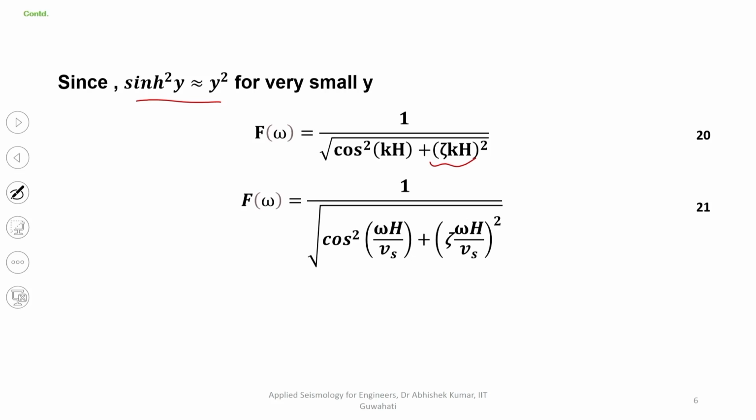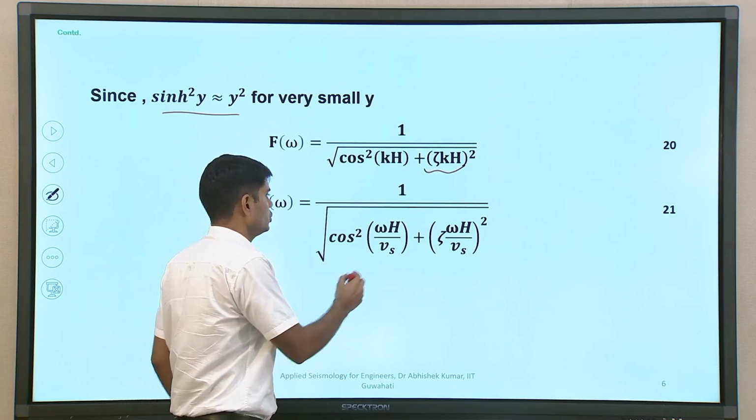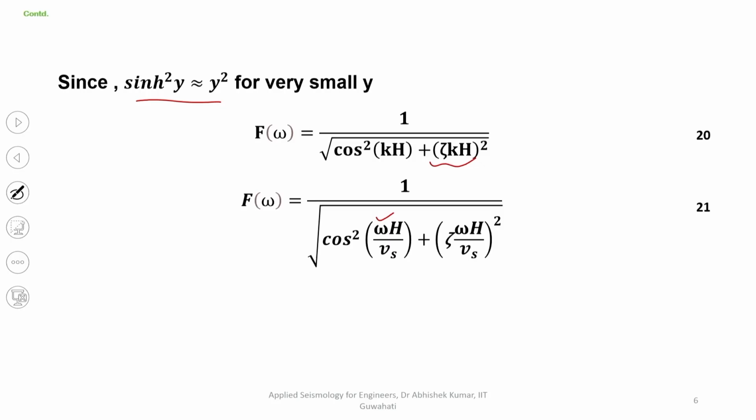Now, here we can see the value of transfer function, or the modulus of transfer function. When we go for finding out the modulus, that will make sure that once you go to the surface getting the Fourier spectra, you are getting real parts. So, you see over here you have the value of omega, which is representation of how many frequency contents are available in your external loading condition, what is the shear modulus or what is the shear velocity, or how much resistance because of shear modulus of a particular medium is available, and the last one is damping ratio, which is directly a function of the rate of loading, how much it is available.